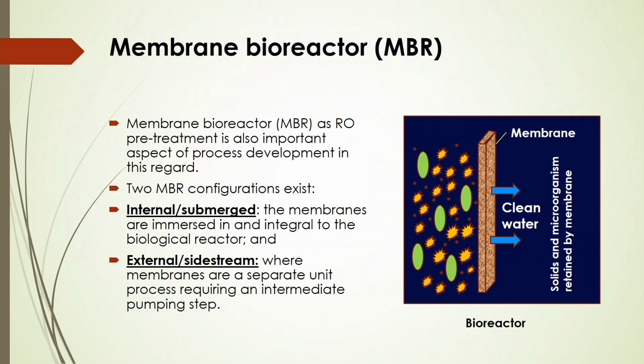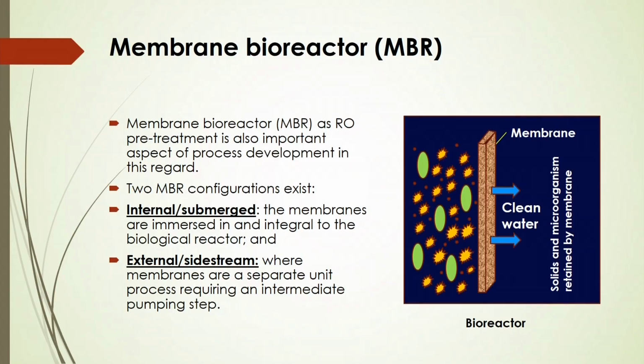You will see the internal submerged bioreactor, where the membranes are generally immersed in and integral to the biological reactor. In the case of external or side stream membranes, the membranes are a separate unit process that requires an intermediate pumping step. That is why these two types of membrane bioreactors are important for process intensification.